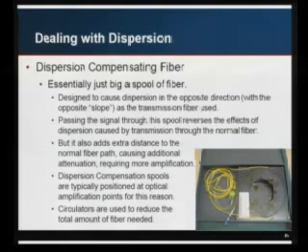To deal with dispersion in fiber, like I said, there are different types of fiber. There's fiber with a positive slope and fiber with a negative slope. Basically, you end up using one type of fiber in your deployment, and then you use the other type of fiber in what's called a dispersion compensation unit. It's basically just a box with a big spool of fiber in it. You run your signal through it, and it disperses it the other direction. It counteracts the dispersion that you encountered when you ran it across the long haul.